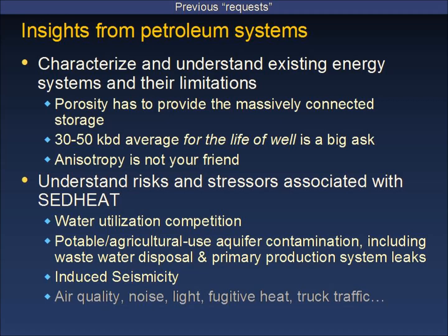Right? I've put a raft of other considerations here as lesser by graying them out and by putting them at a space on the slide where those of you in the back row probably can't even see them. But one of these, if there's a significant non-condensable gas component, as is likely in carbonate systems, then air quality or non-condensable gas disposal is going to be an issue. And so the question is, how can we take that liability and design a producing system that would turn that into a profit stream somehow?